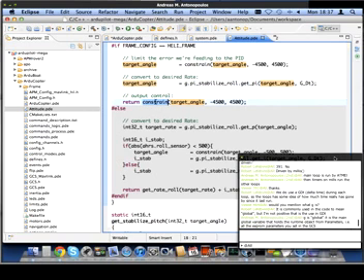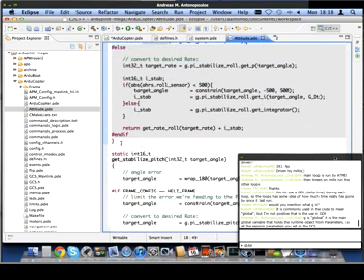So say, for example, it's a 15 degree error, it'll come back and say, okay, I therefore want to roll over at 35 degrees per second, something like that. That would come back from that PID controller into the target angle. We then take that and, you'll see right at the bottom of the function, we actually pass that into the get_rate_roll right there.